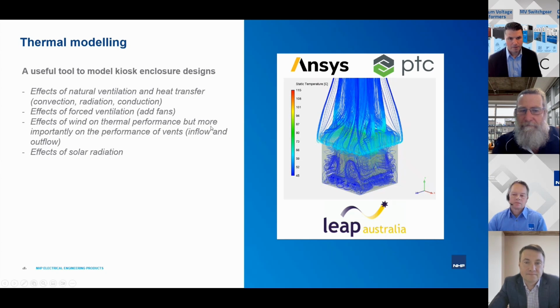Okay, so we know from what Dimitri said that we need to get a very, very good class rating. Class 10, which is what they're aiming for, is very difficult to achieve, and it'd be difficult to achieve anything better than that. Certainly can't achieve class 0. So we are aware that to get the best cooling effect on the transformer, we need to have good air entry flow through the bottom vents. We need to have good direction of airflow over the transformer, over the parts that need to lose the heat. And then we need to get that hot air out of the transformer as quickly as possible. We want as good laminar flow through the enclosure as we can get.